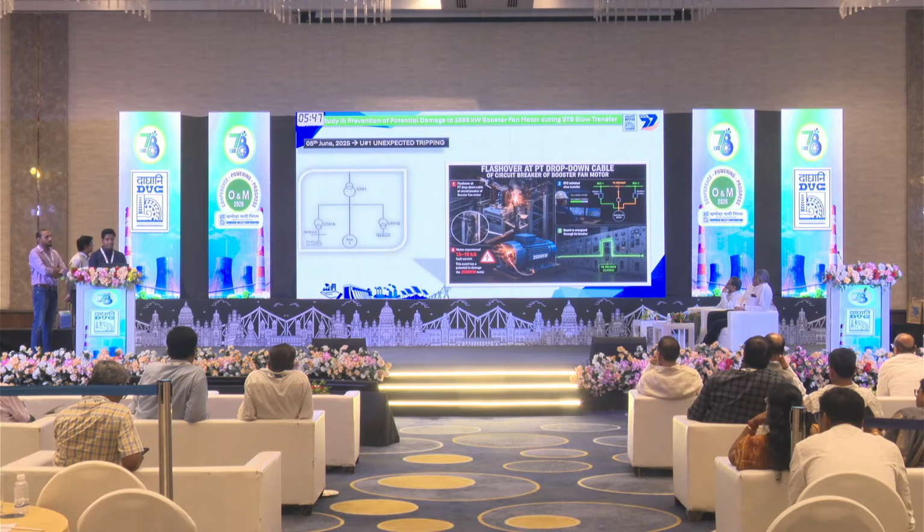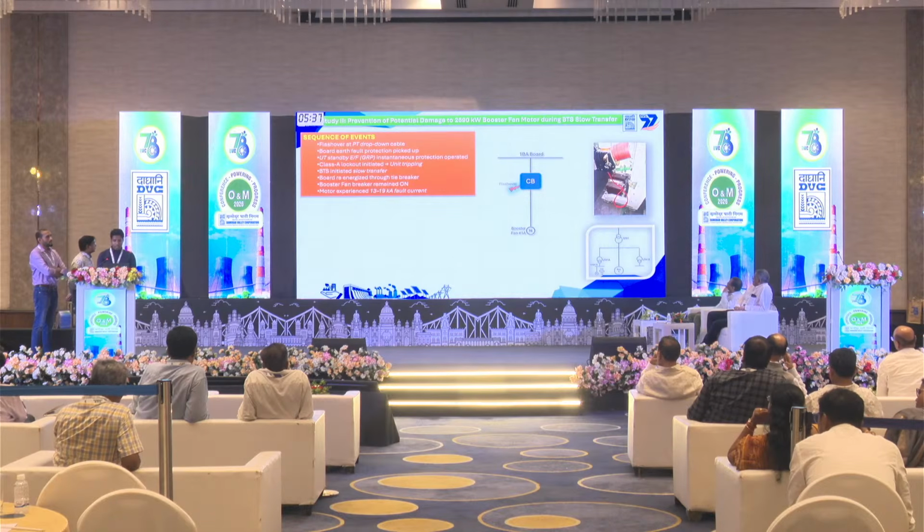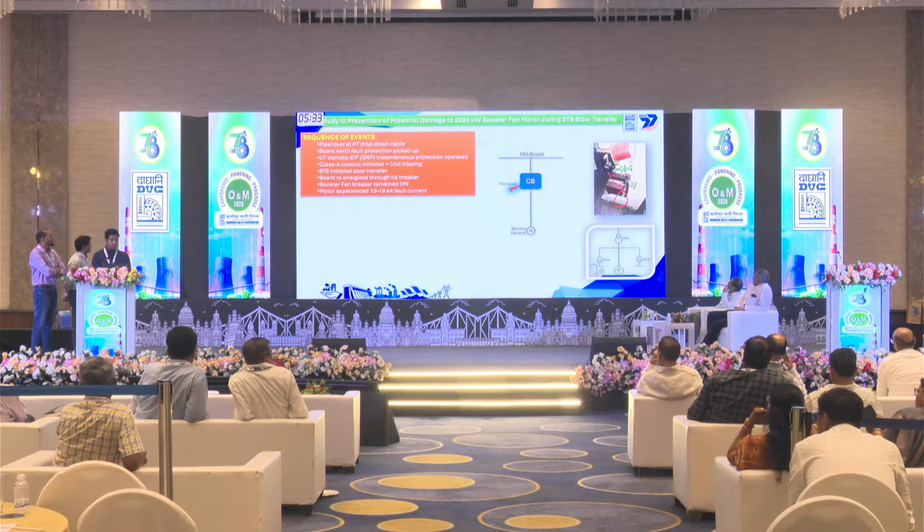Now coming to the second case study, it was 5th June 2025 when KTPS Unit 1 experienced an unexpected tripping that originated from the booster fan motor. Actually, in this PT drop-down cable, there was a flashover. And due to that, the UT standby earth fault protection relay at GRP operated, and due to that, the unit tripped in